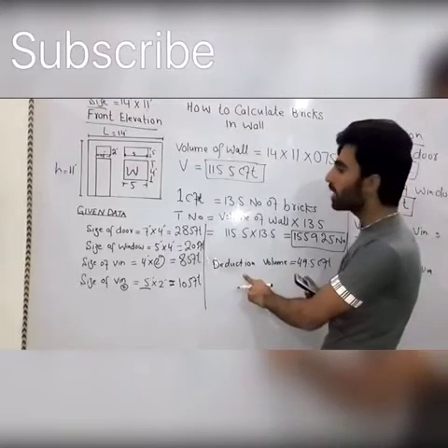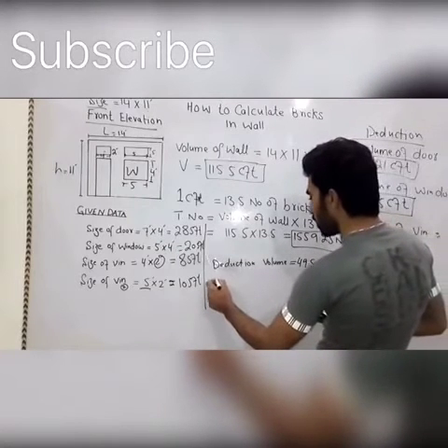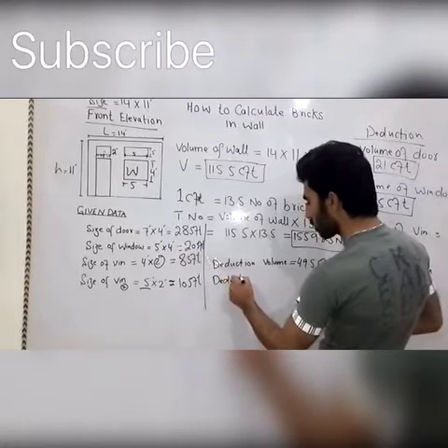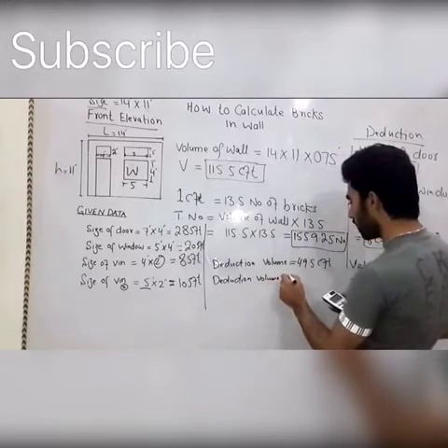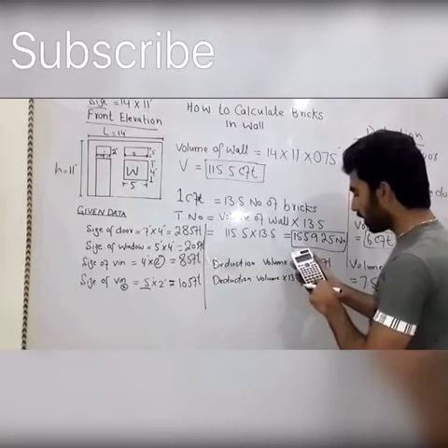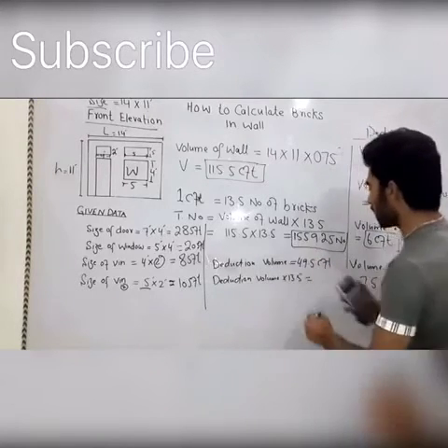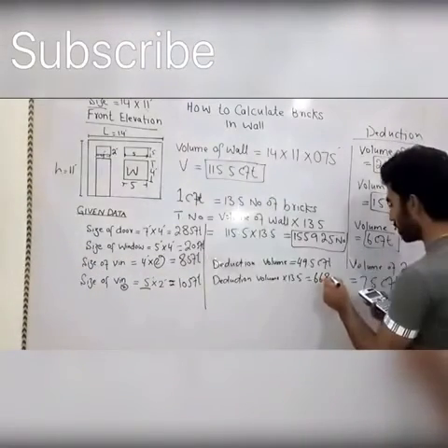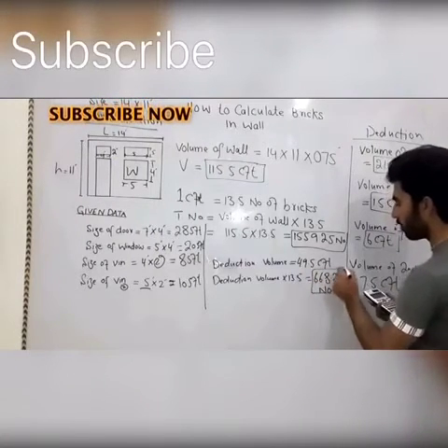How many bricks will be deducted from the total numbers? Okay, so we can say deduction volume multiplied by 13.5. It will give you 668.25 numbers. Okay, so these numbers will be deducted.